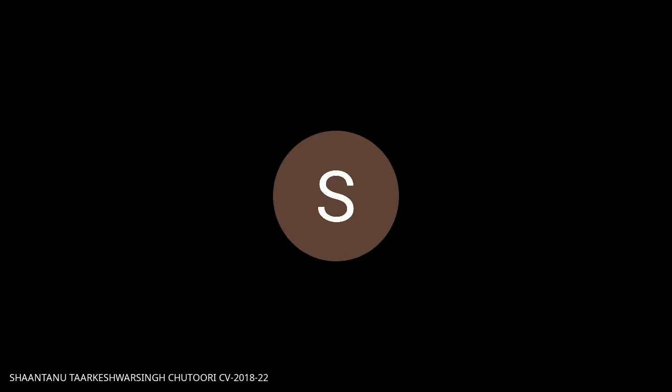There's a sensor which detects plastic specifically also. That is the capacitive sensor, the first sensor, because usually all materials have a dielectric constant. A plastic's dielectric constant will be at a certain number, and metals will be relatively high. So whenever a metal passes, it gets checked as metal because of its dielectric constant and is thrown in the metallic bin, whereas the plastic just gets passed directly onto the moisture sensor.